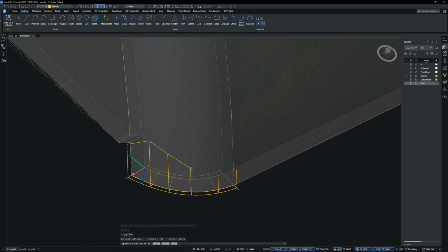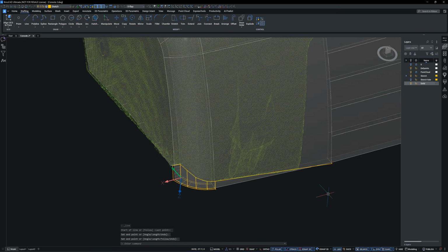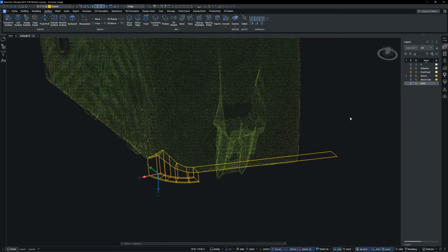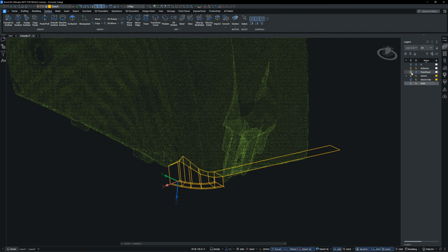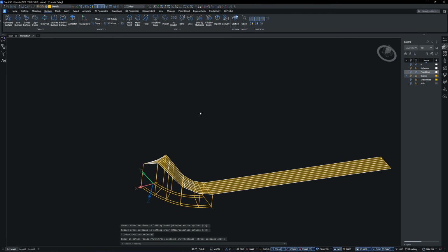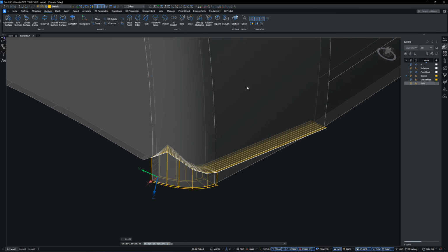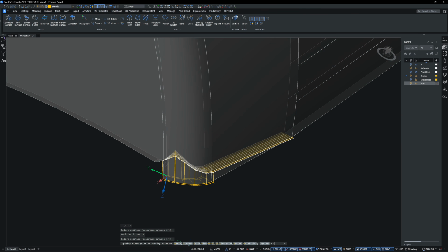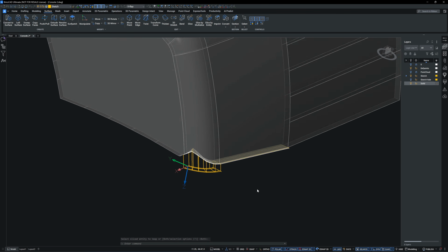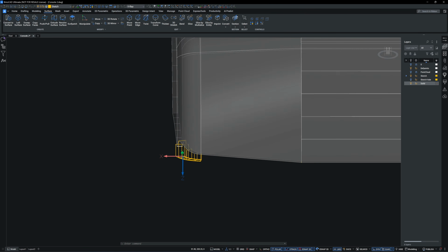Then I draw lines and arcs along the tips of those vertical segments to create 3D curves. The 3D lines are placed slightly wider than the wall to be cut, and I also create matching 3D curves for the inner wall. Then I use the outer and inner wall 3D curves to loft a surface, which I apply to slice the solid. The result is a very clean cut, even better than the original part, which relied on multiple extrude cuts across different planes. That method is slower and produces poorer results.